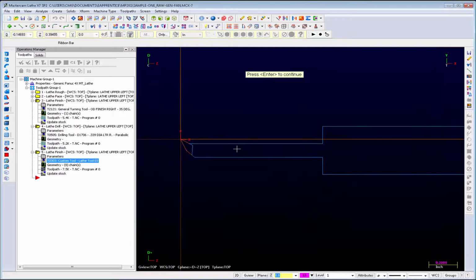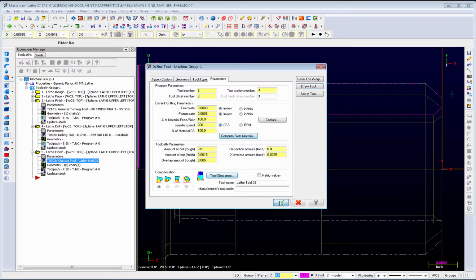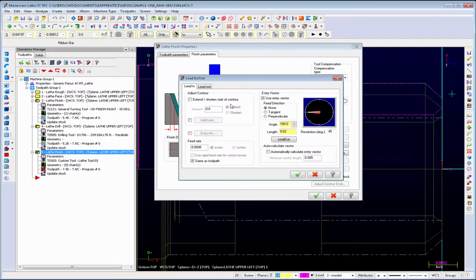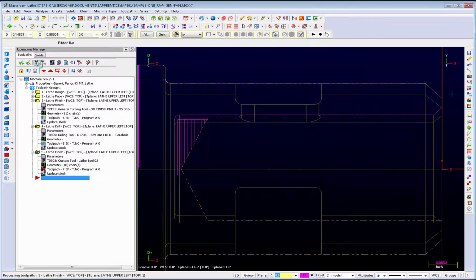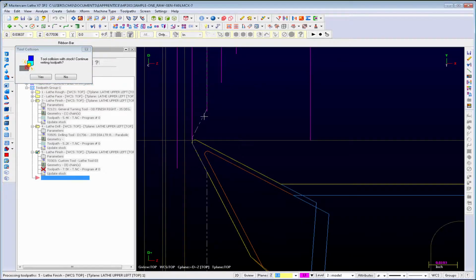So once more, draw tool. You can see that our clearance angles are good. And for lead in, see what happens if we go 12 thou with the lead in. So we've still got this issue here just because of the tip of the tool.